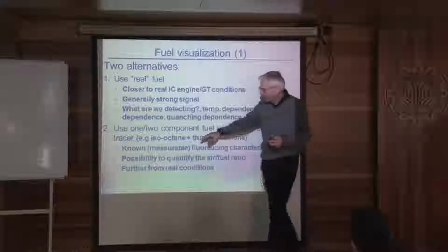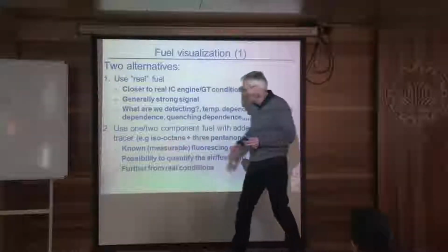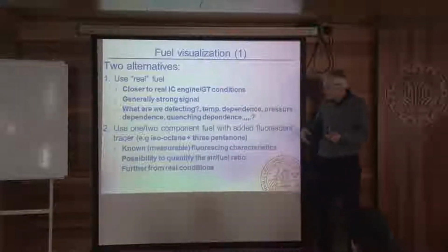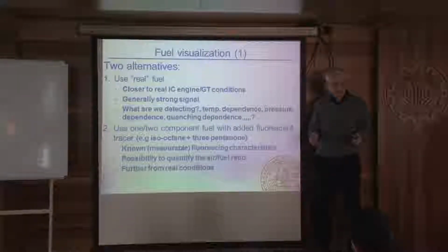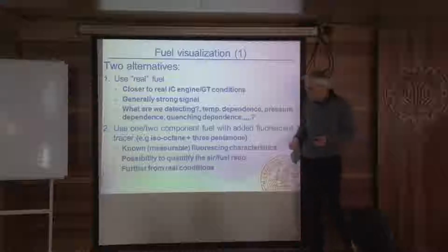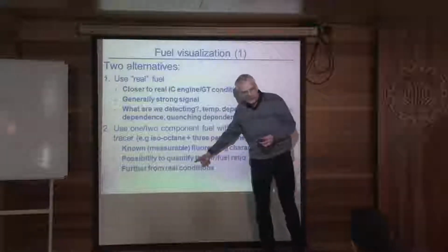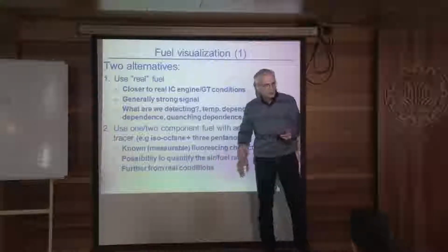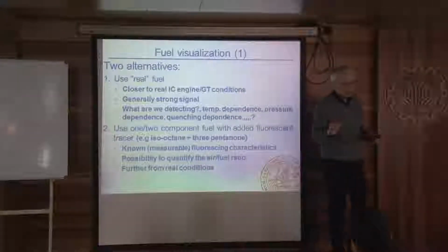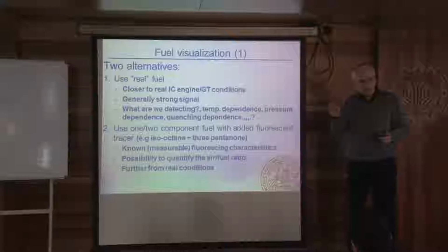And the nice thing with this is that then we know we can measure and estimate the fluorescence characteristics. We can quantify the air-fuel ratio. We just don't get nice images. We can quantify this to get, at a specific point, what the actual air-fuel ratio is.